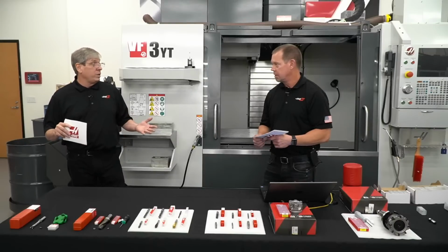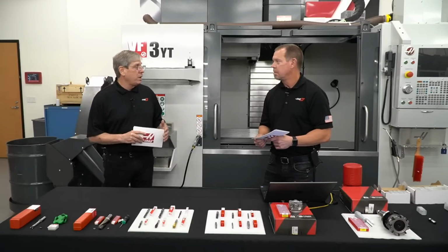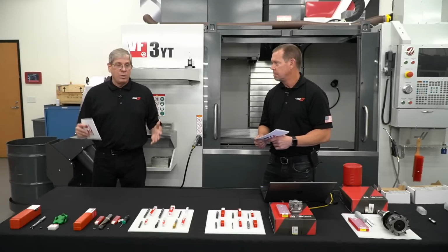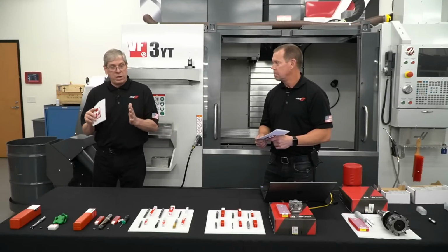And then your team set up video cameras inside of the machine that we were testing. Right. So every mill cutter that we tested, there's a cutting video that goes along with it. That's right. And then we were able to, using that, we programmed all of the tools to run right in the middle of the recommended speed and feed from the manufacturer, to make sure that once you got this tool and you ran it on this material, if you plugged in the middle number, it would work. I promise you it will work.